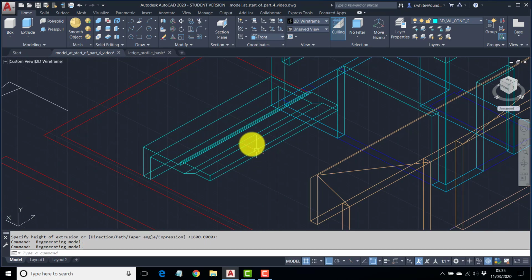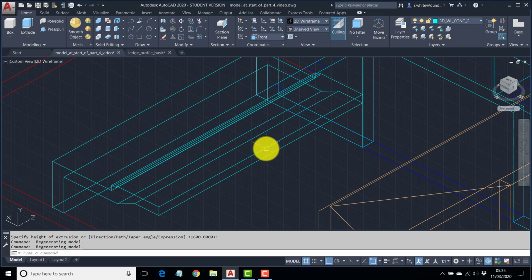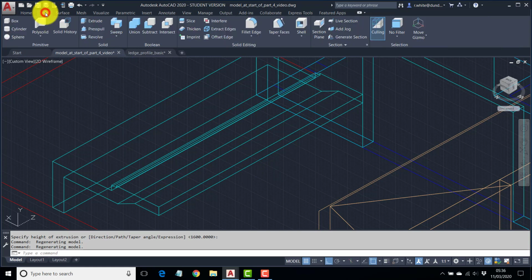This is a bit harsh, chances are you might bang your knee right on the corner of that concrete. That would be pretty painful. So what we're going to do is soften these by filleting with a radius these solid. Okay, AutoCAD's okay at this. It's not quite as good as something like Rhino at doing this kind of job, but if it's a fairly simple operation like this one, it would be okay. Okay, so if you go to solid, and then on the solid editing area we've got fillet edge.